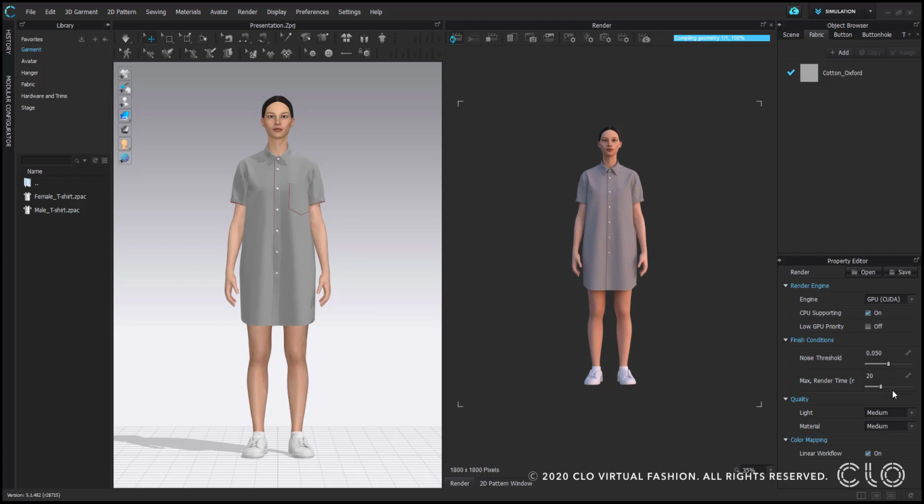Below that is max render time. On average, the rendering process only takes about 2 minutes when using the default settings for image and video properties, lighting, and render properties. However, the render time differs when the properties are modified. Some things that can contribute to longer render times include using large texture images, material properties such as fur, and/or any additional geometry in the 3D scene.